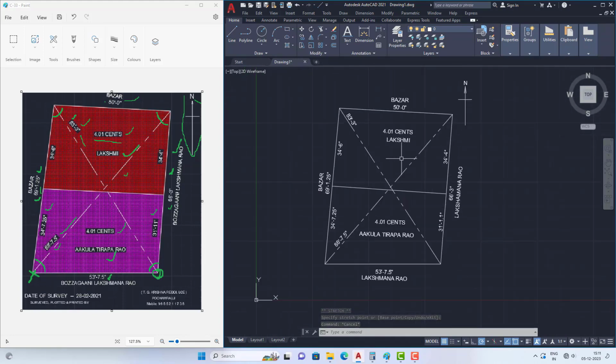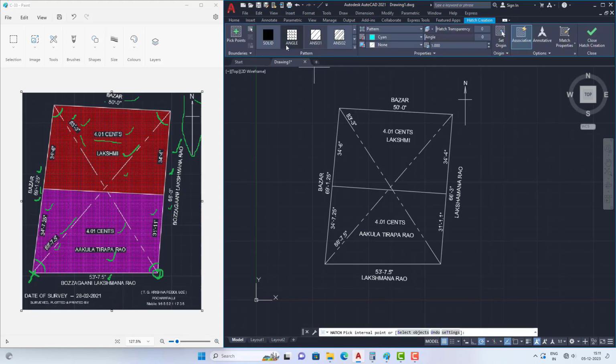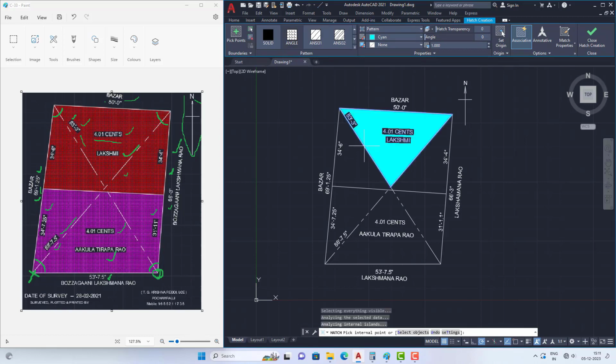And now check, we have completed this drawing, and we need to represent this in this type of field or whatever. I am going into the hatch command, and I am selecting this angle. There is angle over here, and I am selecting this internal points, and I am giving the hatch value so that it will be appearing good.